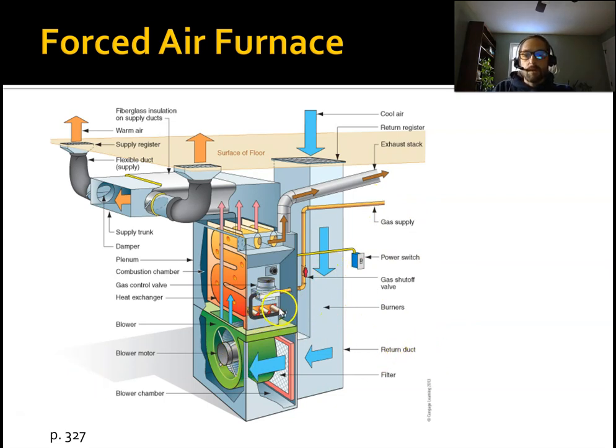So then you have your combustion, and in these burners there's a little igniter. Usually the new ones use an arc. There are two pieces of metal, and it creates a spark, and then you spray the gas across that, and that's what ignites the gas. That heats up, and then the hot gas goes through here and heats up the heat exchanger.